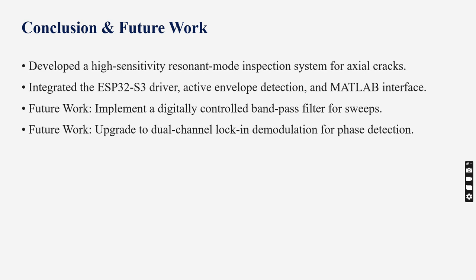In conclusion, we have designed and validated a resonant mode inspection system optimized for axial crack detection. The series resonant tank and the H-bridge drive successfully translate micro impedance shifts into large voltage drops, which are rectified and logged in real time.